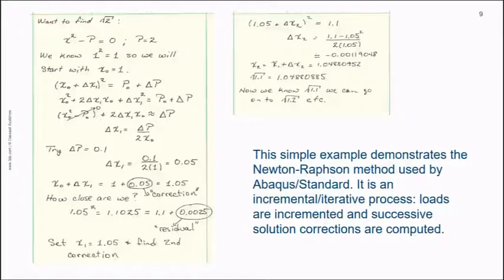Now, in a structural analysis like Abaqus Standard solves, it's very well known that you would start from the base state. If you have an undeformed model or a model with no loads yet, then that would be the initial state. And then if you run some load steps, then the base state for step 2, say, is the state at the end of step 1. But whatever we're doing, we know a solution.